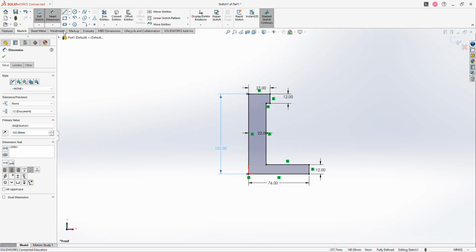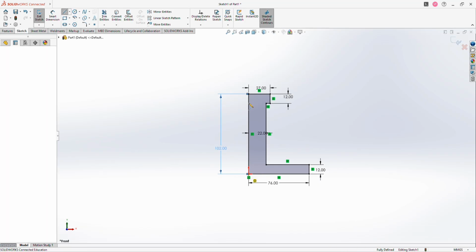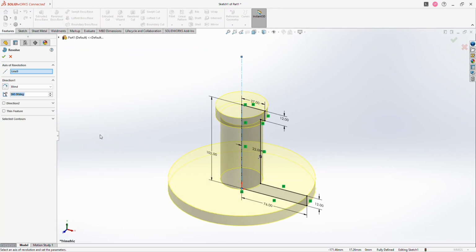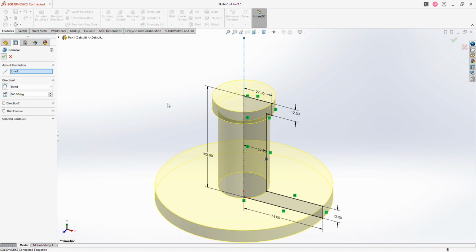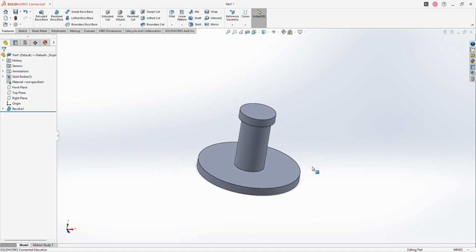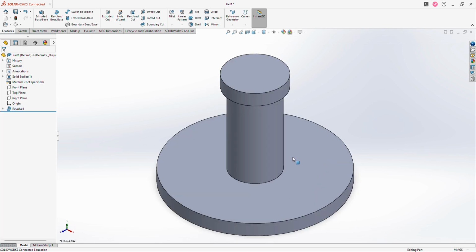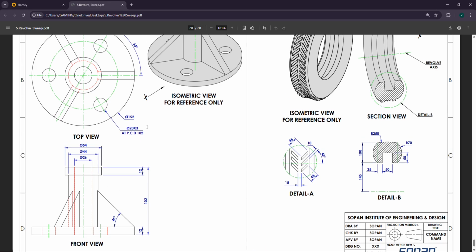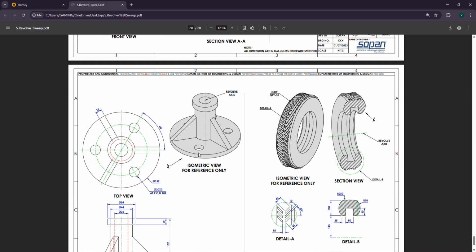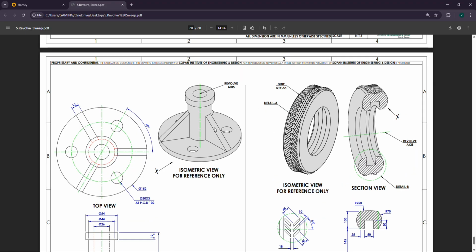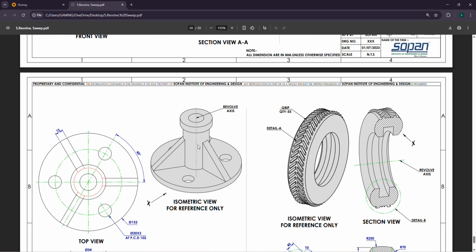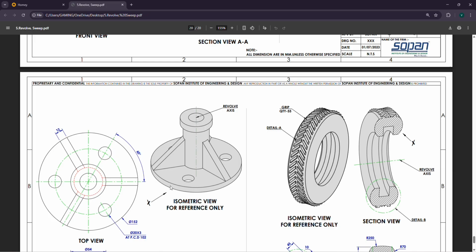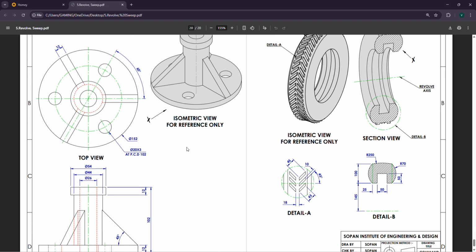And we are going to create a vertical axis, giving a construction line vertically upward. And using a revolve feature, selecting all the regions, we are going to get this sketch, right? Viewing it in an isometric view, we'll be able to see this, right? So now, this is a very interesting case, because the circular rib over here is not attached to the top surface, but it is somewhere in between on the vertical axis. So we just need to calculate the vertical length of this point, right?